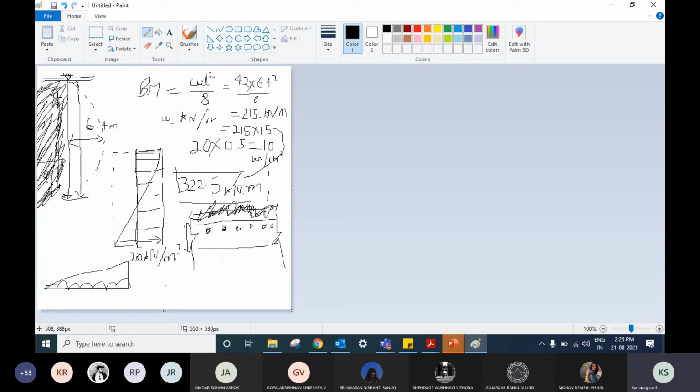What do you mean by minimal reinforcement? Any reinforced concrete section should have some reinforcement. That is given in terms of percentage. If you refer to the IS 456 code, it could be 0.6 percentage of the cross section of that particular shape, or 0.8 percentage of the cross section, right? But first we'll focus on the important parameter, which is the overall thickness, X over here, and what the reinforcement bar sizes are.